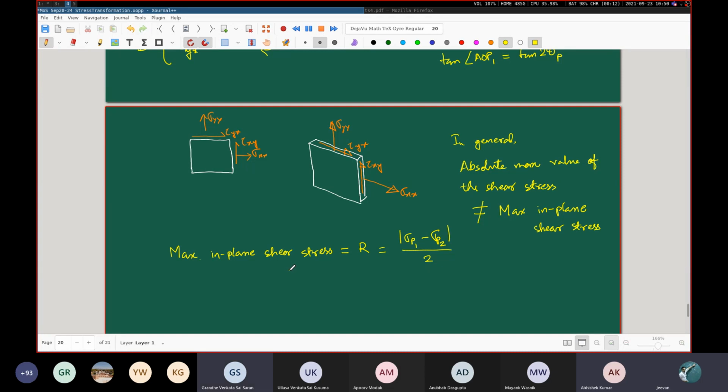It may or may not be, depending upon the. No, there is no depending. You're supposed to know the answer here. Consider the relation between sigma P1, P2 and P3 in decreasing order. That's the thing. There is something hidden here, but hidden right in front of your eyes. What is sigma P3 here? It's 0. Why? We are considering the stresses in a plane.